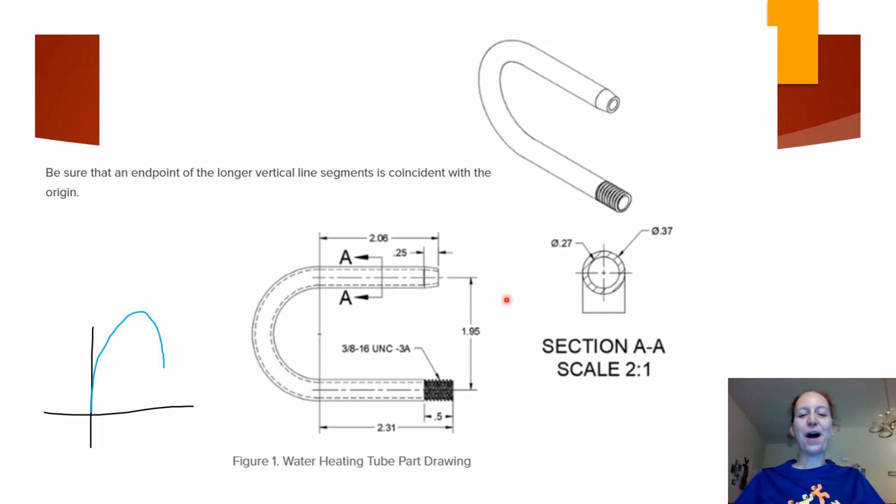So they have you construct an axis through the pipe and then revolve a shape. If you watch the video, I was able to get that to work, but it does require some pretty advanced geometry where you have to construct a plane through an axis and a point, and then you do have to guess at how much taper there's supposed to be on it.